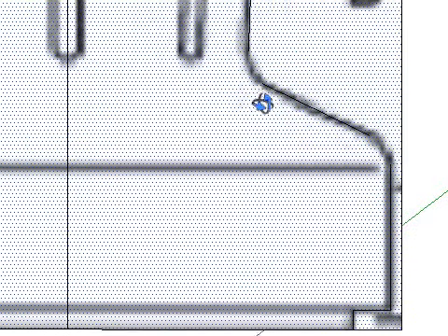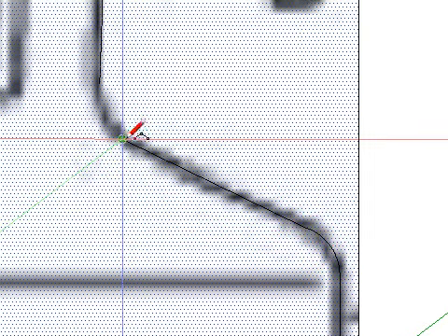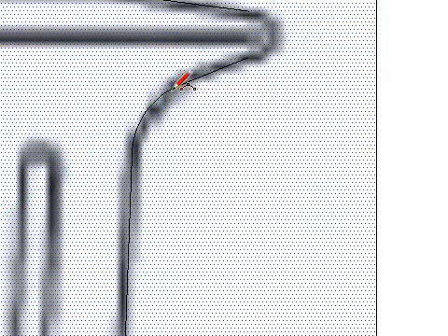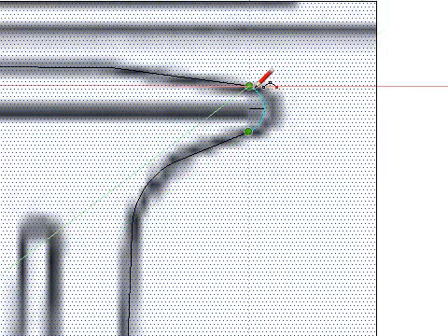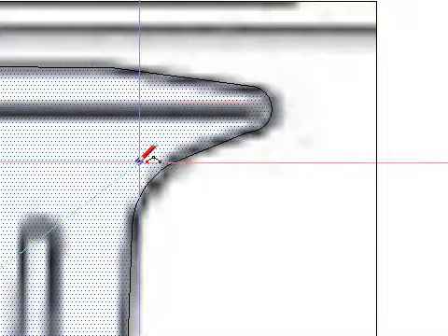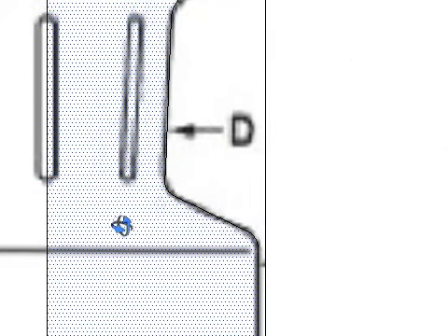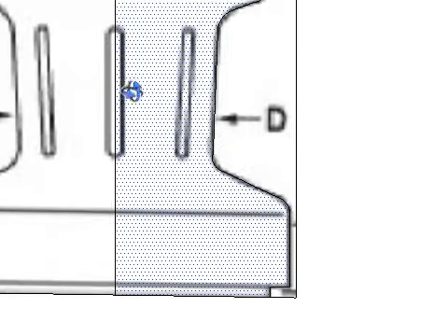And there, almost done. Up and over, right to the center, down to the base, and over to my starting point. So now I add the arcs with the arc tool, and it nicely pretty much lines them up the way you want them. I'm going to make this one a half circle, and now you see I have the cross section of the winch, the half cross section.